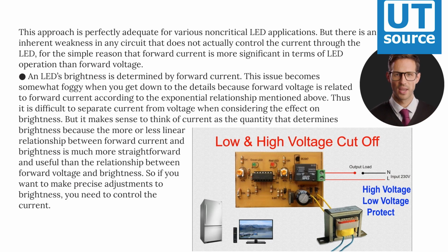any circuit that does not actually control the current through the LED, for the simple reason that forward current is more significant in terms of LED operation than forward voltage. An LED's brightness is determined by forward current.